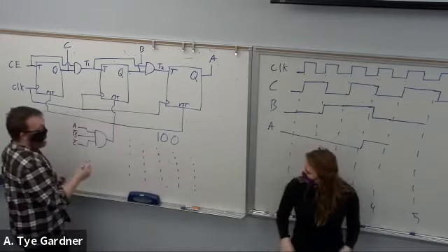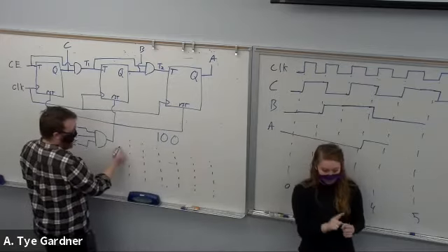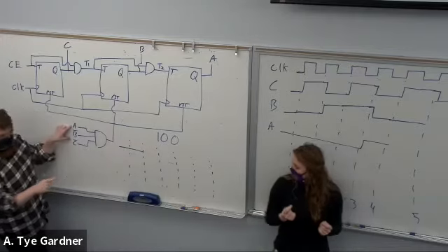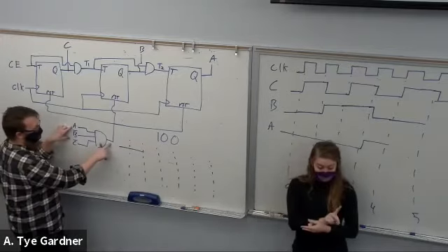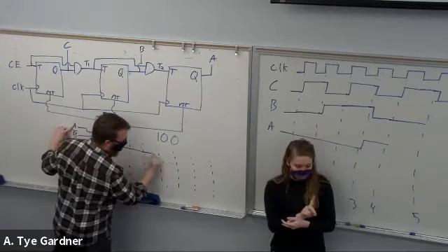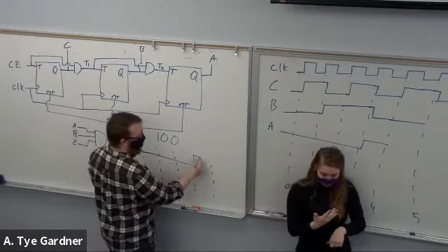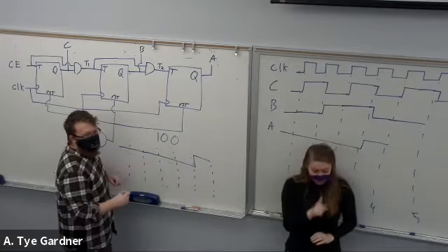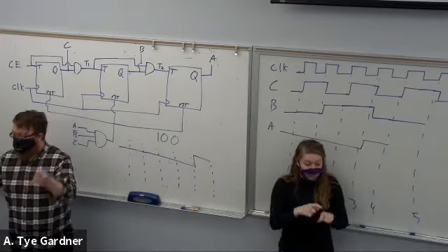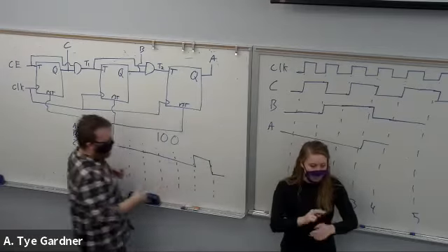So the AND gate, because I'm counting to 5, is 0, 0, because this is not true, right? So this is the output of this AND gate. It just is not true, and it does that 5 times. It then becomes true, and then on the next rising edge has reset things, so it's no longer true, and goes back to 0.